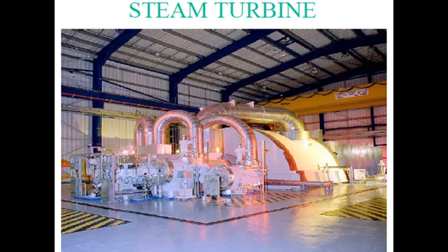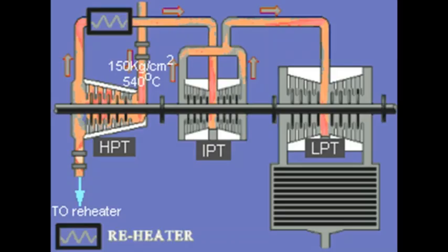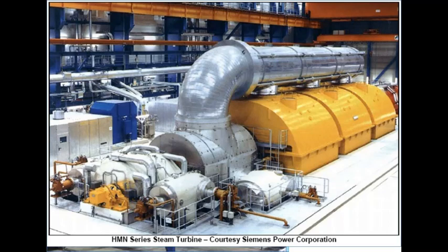So in the HP turbine we have high pressure expansion, and we have an arrangement to control the steam injection within the turbine by governing, and we have nozzles. Besides that, there is bleeding from the HP turbine. These bleed steams are used for the regenerative feed water heating system, particularly high pressure heaters, where a non-contact type heating arrangement is there.